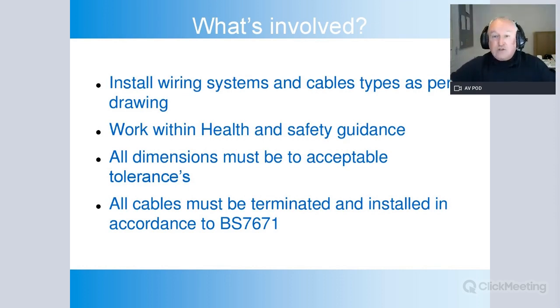For argument's sake, here's a little socket. If you've got to install this socket, and you decide, you know what, I'm going to stick it there. But in reality, the drawing says it needs to be there. The reason for that is, what you don't particularly know, there might be a pipe here. You put your socket in, and suddenly that pipe's in the way. You can't do that.